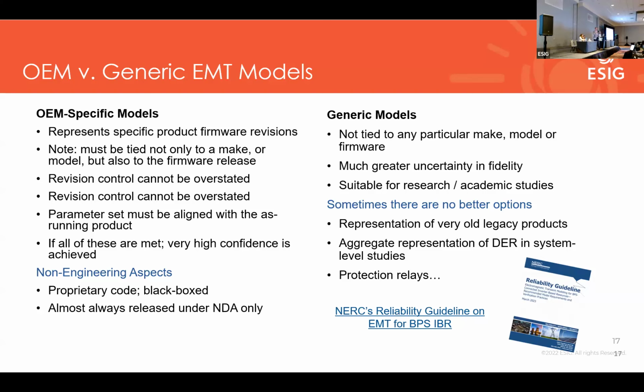I think this is some of the rigor that we're seeing and really trying to drive. If we're at this level of fidelity, you really have to run it to ground and know what's on your machine and what's in your desktop simulation and make sure that those are aligned. Because we've seen too many instances, as Julia pointed out, where we thought we had it and we didn't. And we can't field test faults, or we're unwilling to do that for good reason, so those differences don't show up until you have a real grid event.